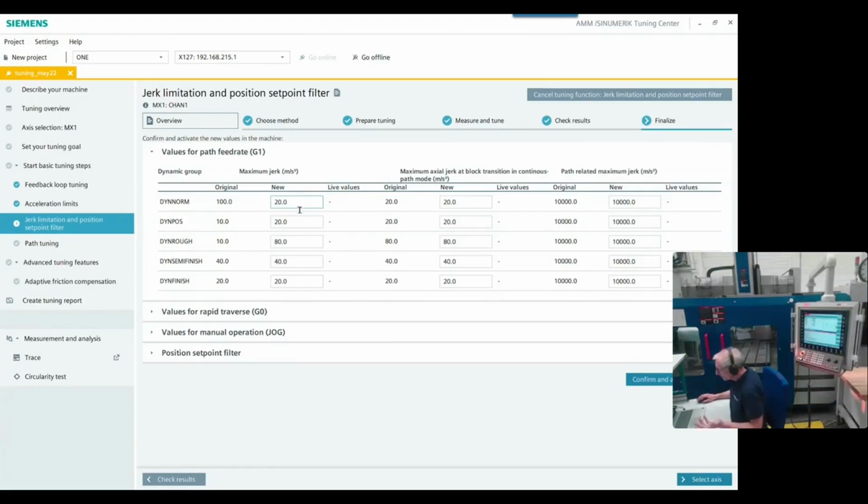And anyway, if you do roughing, you know that more cutting processes will follow. So you don't care about some micrometers of vibration on the surface if more programs will follow anyway to cut.